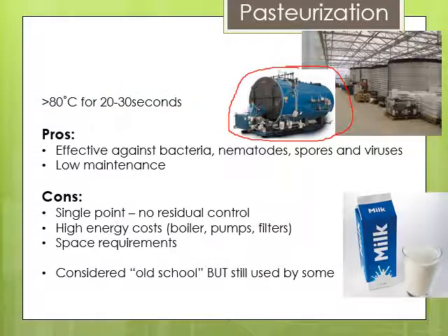Commercially, milk is all pasteurized. They heat it, same thing. They have high temperature heat exchangers with hot water from a boiler, and the milk passes through it. And the milk is heated up to 80 for a short time, and that kills not all the bacteria. They have only about 5 to 10 second exposure time, but it kills 95% of the bacteria,